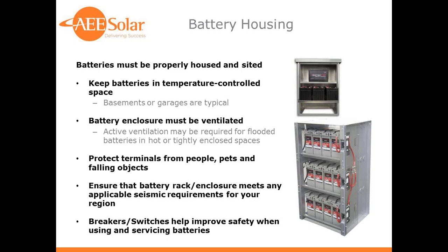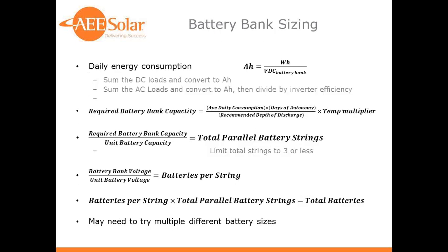Okay, we're going to get a little bit into battery bank sizing here. Typically, we look at what the daily energy consumption is. Again, working with off-grid, we're dealing more on a day-to-day basis. This is a lot different from grid-tie systems, which are basically just trying to produce a certain number of kilowatt hours over a year. It's averaged over a year. In an off-grid situation, we're really dealing more day-to-day, so we really have to have figures that are more attuned to the day-to-day operation of the system rather than just yearly energy production.